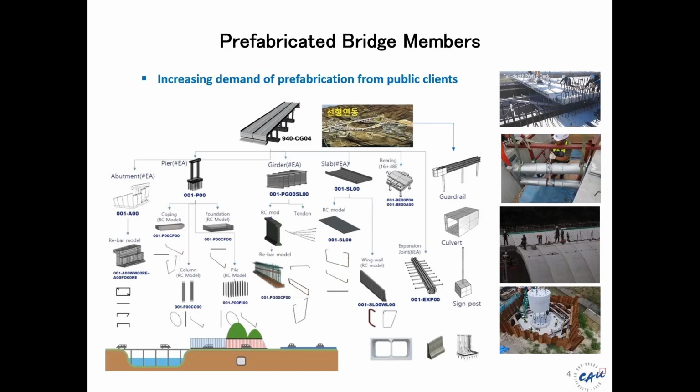Continuously in Korea, we have new prefab bridge members, including full depth precast decks and lateral beams, which can adjust the length a bit, around 400 or 500 millimeters between girders, because the girder may have some lateral deformation by pre-stressing. And we have precast tunnel arch and also precast bridge columns. So all the new prefab members are implemented in real bridge construction in Korea.